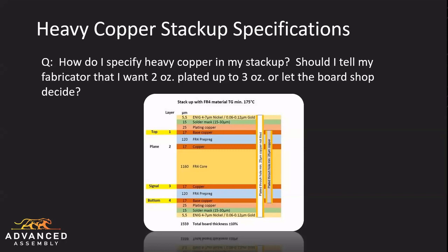However, older designs that ask for 2/2 material that's plated up to 4/4, ultimately this is just going to end up in additional steps that the fab process has to assume, and then ultimately it's just going to cost more. What I meant with that is that I've seen drawings from the 90s, early 2000s that have their legacy designs. Typically these are DoD related, where they want 2 ounce inner layers as a base material and they want them plated up to 4 ounce.